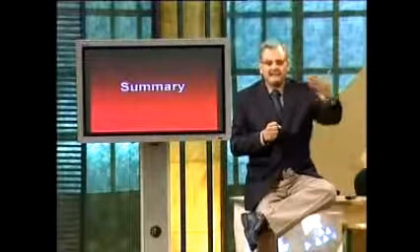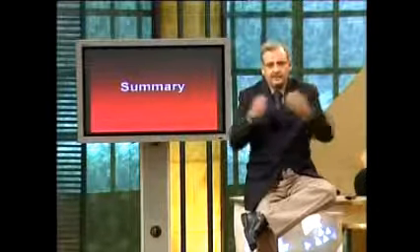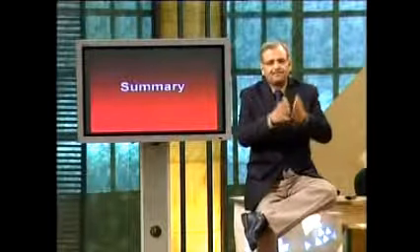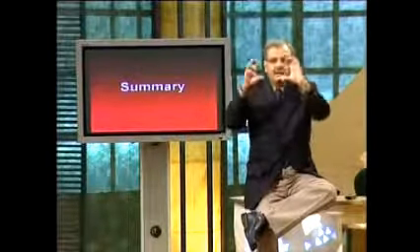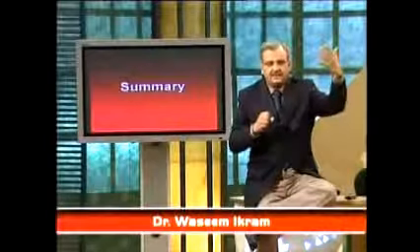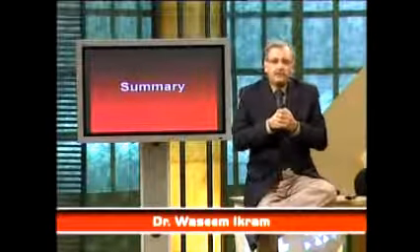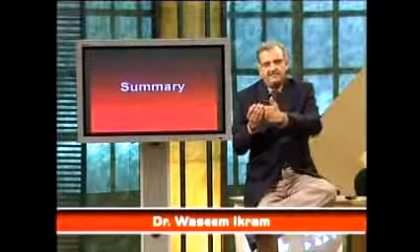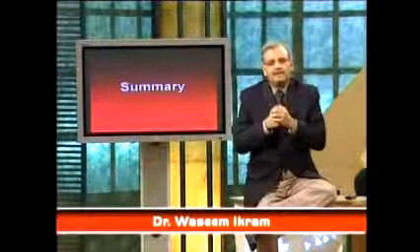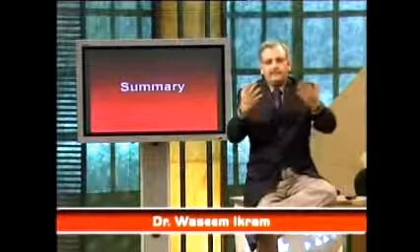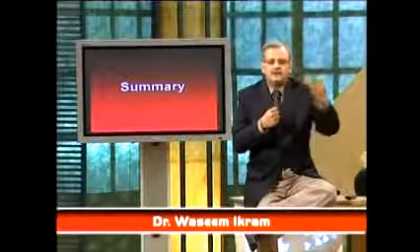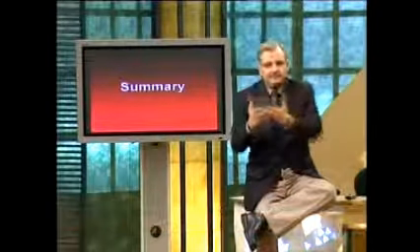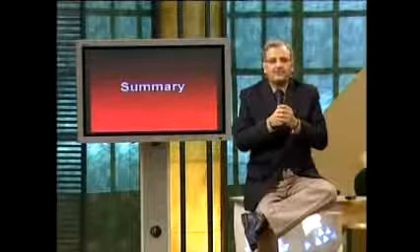We talked about the excess code, which we use in the floating point implementation. We talked about BCD code, which is used to represent decimal digits in binary. Again, applications are to display decimal digits on 7-segment displays. We talked about the gray code, which allows only 1 bit change when you count to the next successive value, the upper value or the lower value. We also talked about alphanumeric codes, the ASCII code. The ASCII code allows you to represent numbers, alphabet characters, punctuation marks, and some control characters.